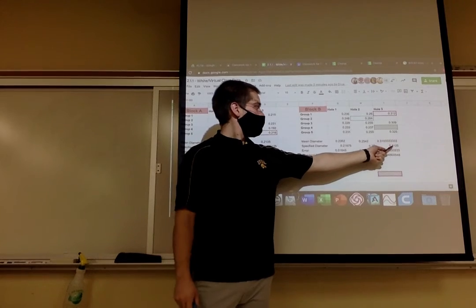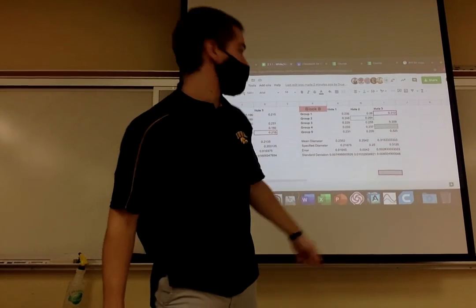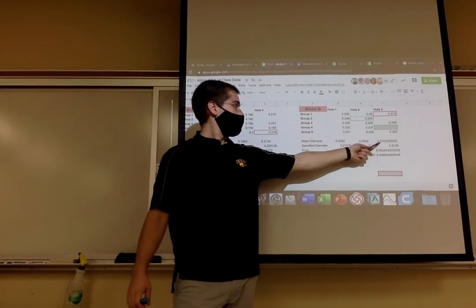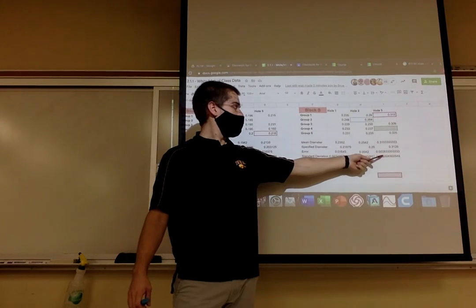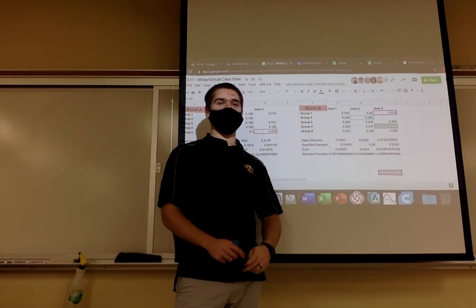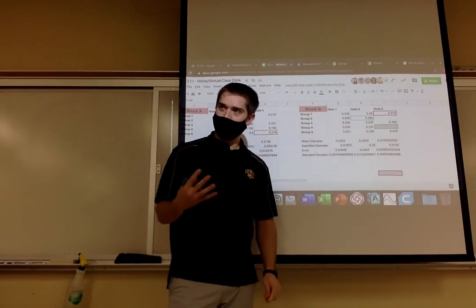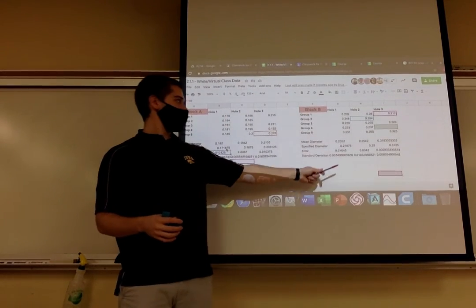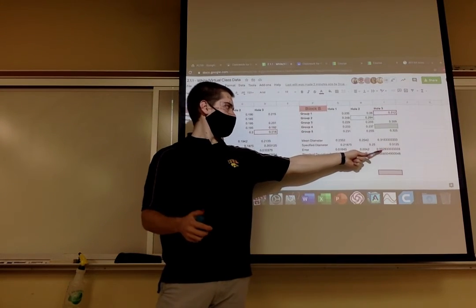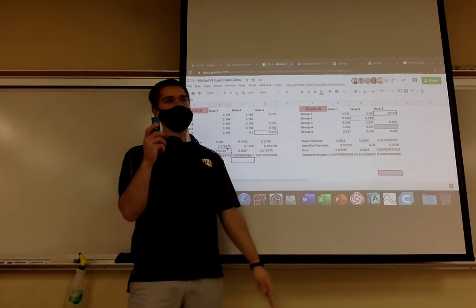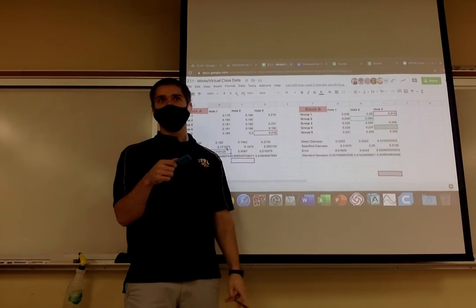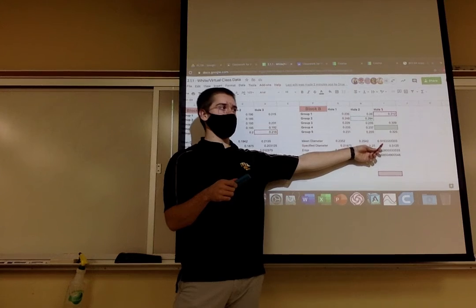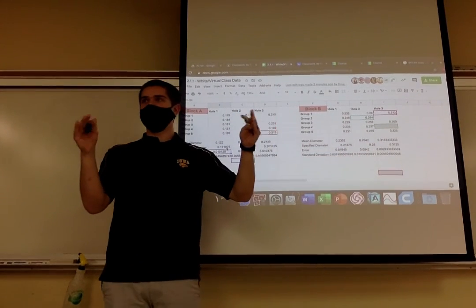This was a 5/16 hole. We were almost 3/1000th of an inch off. Again, if I list my tolerance as plus or minus 0.001, this doesn't cut it. The actual measurement does not fit within the criteria that I've given for my design.